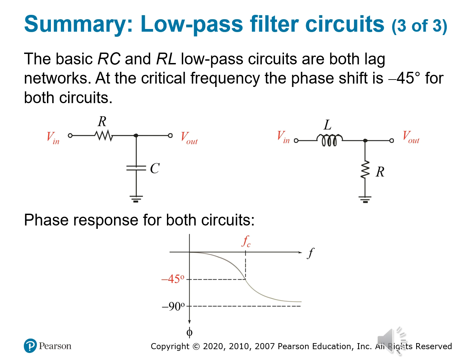Now let's talk about the phase plot. Notice that smooth downward curve. Right? So that's the phase response. As frequency rises, phase shift dives deeper and it approaches negative 90 degrees at higher frequencies. For the RC filter, the capacitor impedance drops, causes more signal to drop across the resistor, and then the output lags. For the RL filter, the inductor's impedance rises, forcing current, and therefore the output to shift with it. Both get to negative 90 degrees, but they pass through negative 45 degrees right at the cutoff frequency.